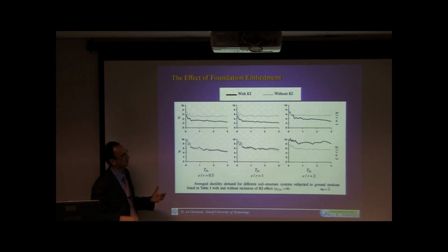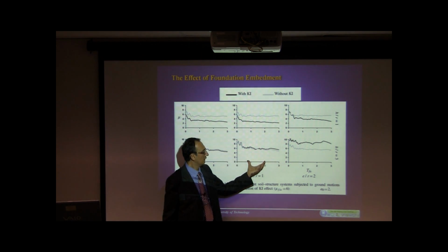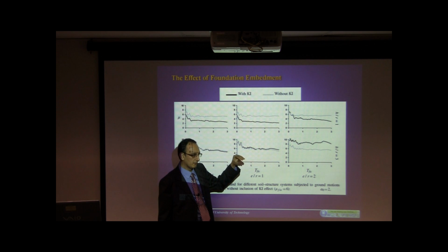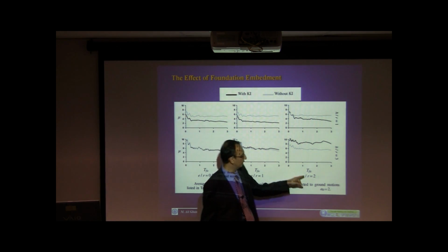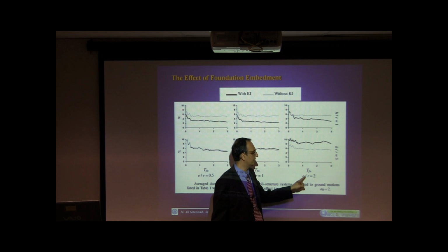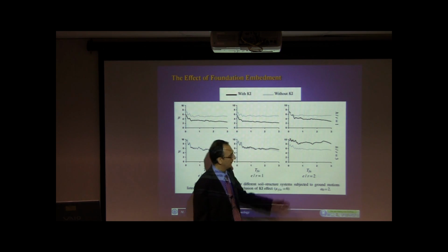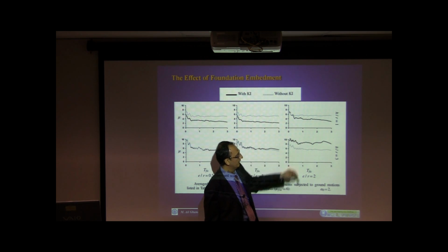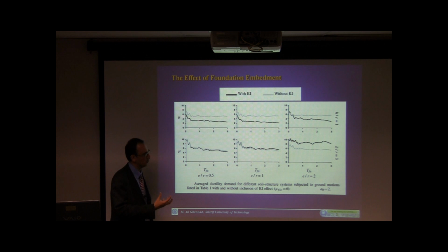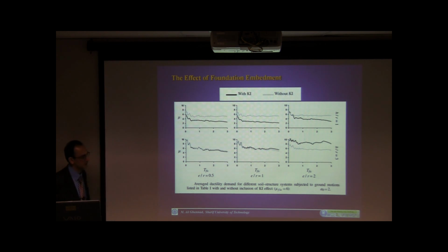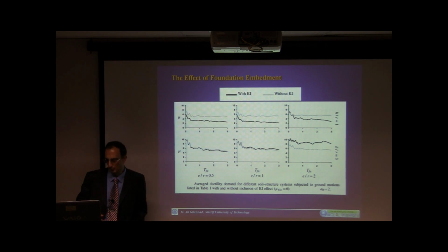But when it goes to slender structures, it starts to lead to higher ductility demand. And especially here for really deeply embedded foundations, one can expect higher ductility demands for the system subjected to the foundation input motion compared to the same system subjected to the free field motion.